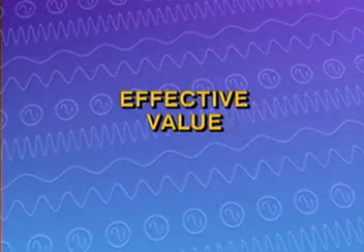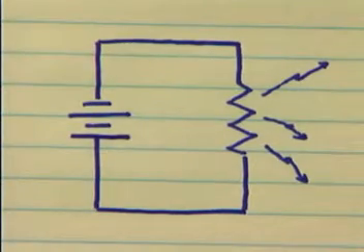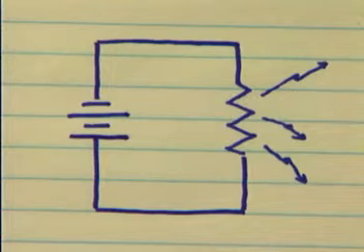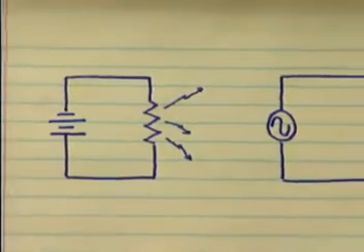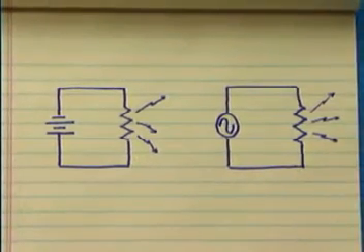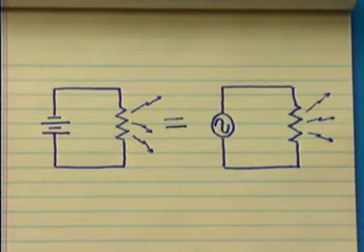While these ways of expressing alternating current values have their use, another method is more helpful. Since electrical equipment can contain both AC and DC circuits, it's important to be able to express AC values in relationship to DC. This is possible using the effective value. In a purely resistive DC circuit, the power dissipated by the circuit resistance is given off in the form of heat energy. For an AC circuit of the same resistance, the value of AC voltage or current that would produce the same amount of heat energy as the corresponding DC circuit is called the effective value.